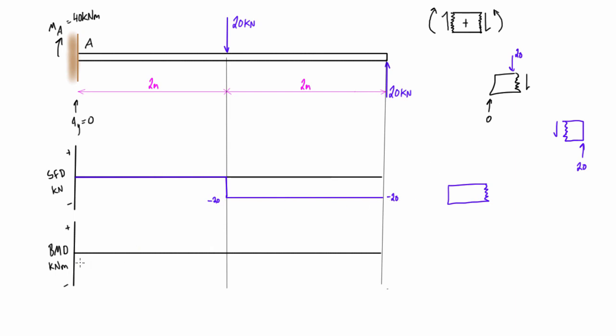But when we're talking about a bending moment diagram, we need to include the internal moments, and where we're starting at a fixed rigid connection, then most likely the internal moment is not going to be 0. It'll be some non-zero number. So when we put on all of our information here, we have AY, that's actually just 0 kilonewtons. We have the internal shear, which is 0 kilonewtons. And then we have MA, acting in a clockwise sense on the beam, which is 40 kilonewton meters.